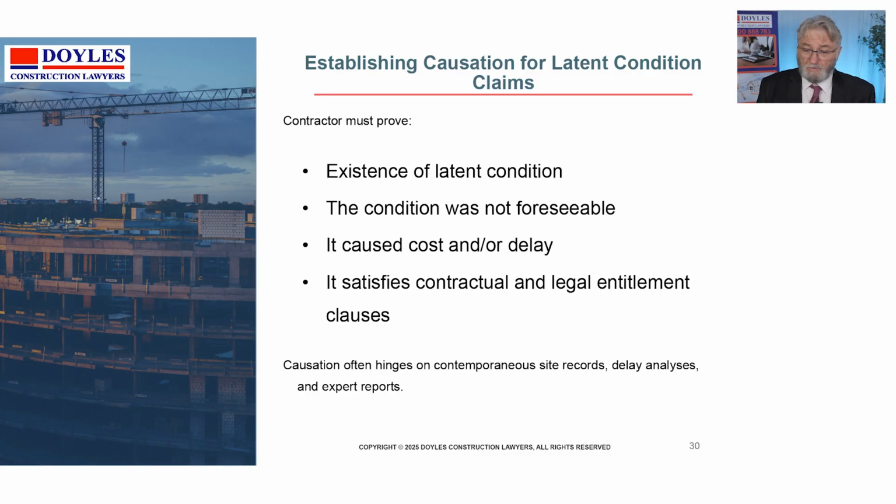Additionally, what you've got to look at is contractual and legal clauses which qualify what you can recover. It's important to go through the contract and prove item by item the requirements of the contract have been satisfied, and that you've got the necessary site records and delay analysis and expert reports to back it up. It's important that latent condition claims are properly proved, properly established, in order that they be well paid.